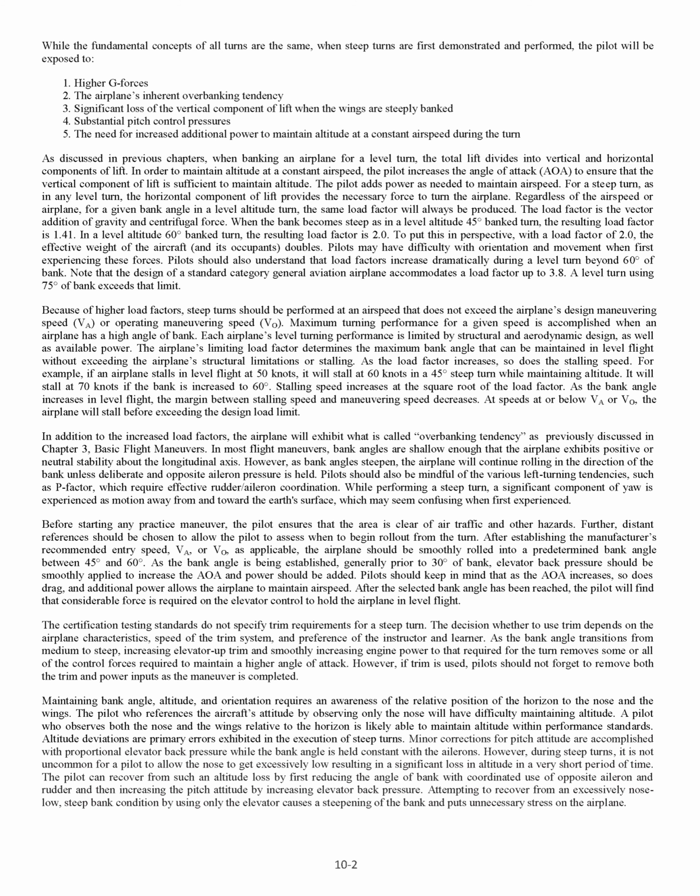As the bank angle increases in level flight, the margin between stalling speed and maneuvering speed decreases. At speeds at or below VA or VO, the airplane will stall before exceeding the design load limit. In addition to the increased load factors, the airplane will exhibit what is called overbanking tendency as previously discussed in Chapter 3, Basic Flight Maneuvers.